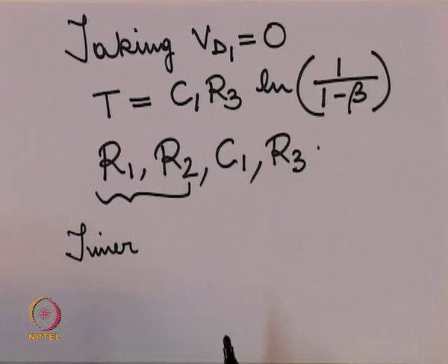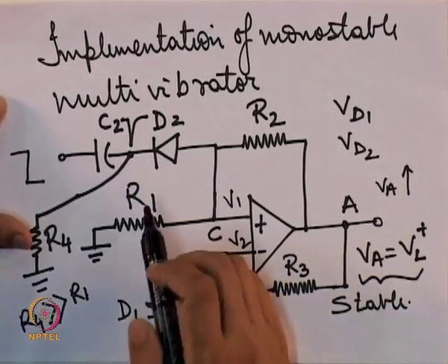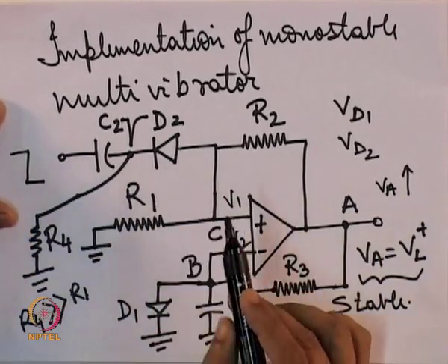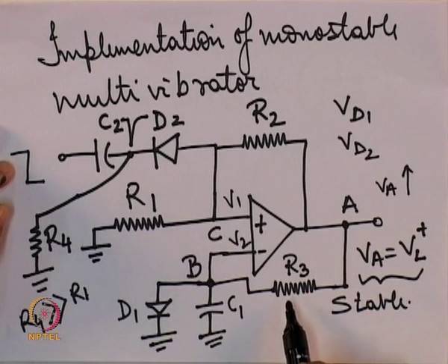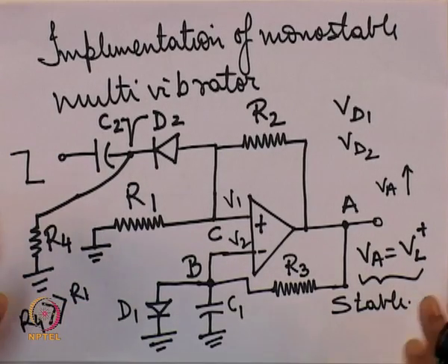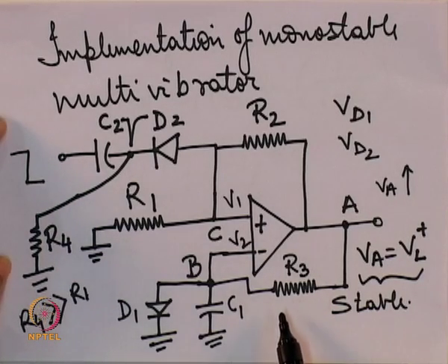For example, coming back to the circuit once again, if we apply a negative spike at the start of an event, and adjust R3 and C1 so that the total time of the negative pulse of this monostable multivibrator coincides with the end of the event, then that will give us an accurate representation of how long the event really existed.